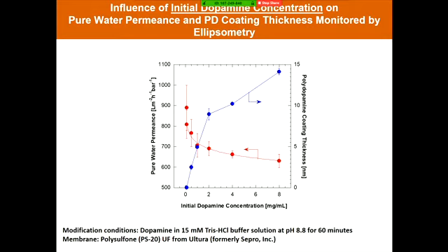And so we tend to do the coating or application of this material over here in this corner, where very low levels of coating give large reductions in contact angle, large increases in hydrophilicity, but minimal reductions in flux so that you maintain as much of the membrane performance as possible.